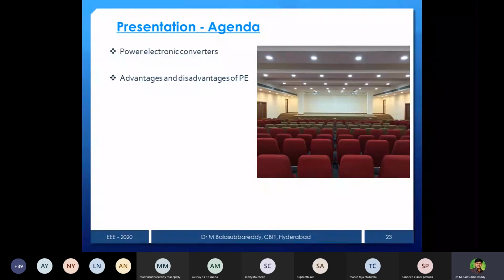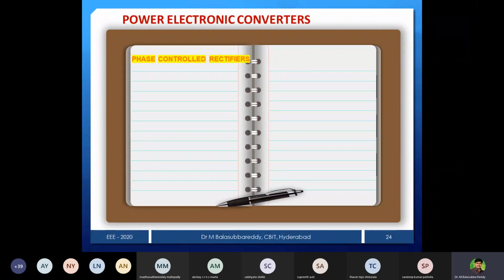Now we'll see another one, the phase control rectifier. Whatever we noticed previously were diode rectifiers, devices, and all these things. Now, what is the function of the phase control rectifier? Anybody? As we discussed, the phase control rectifier converts AC to variable DC. That is its function: AC voltage to variable DC voltage. The rectifier uses line voltage for its commutation.